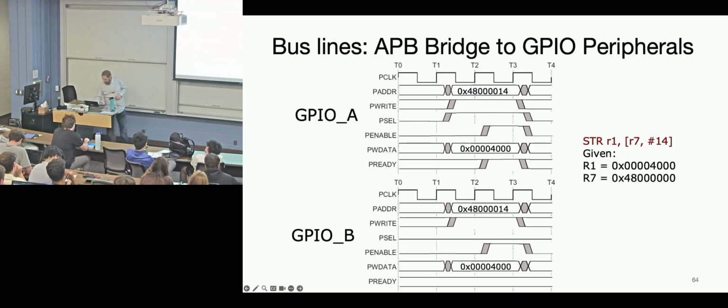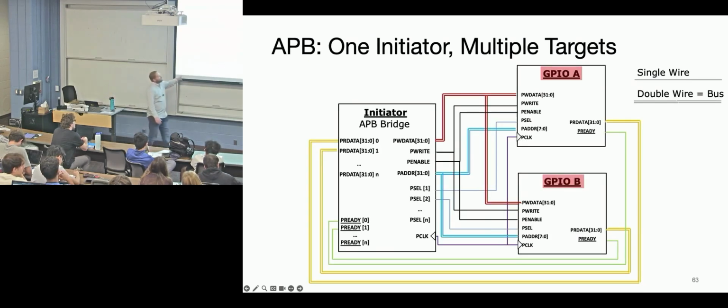And that is why, if we get to here, this idea that there's multiple peripherals, remember they each have their own P-write data bus. So 32 bits, or 32 bus, for each peripheral going back here. That means this thing can take a while setting up this data. The initiator can go off and talk to some other peripherals and have a transaction back and forth. Maybe that peripheral's faster, right? And then it says, okay, well, when I get back to it, then I'll read this data out and do my task. So this is how it allows this thing to be much slower than the other ones.